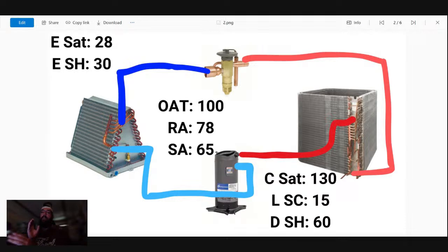So in this particular case, you go do a visual inspection at the TXV, and the body itself is not freezing up. It's just at the distributor going into the coil that you're having the freezing happening, and you're getting a little bit of frost on the body, but it's not happening at the inlet port where the screen would be.